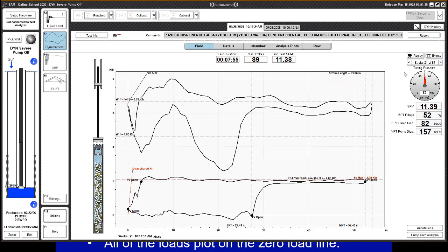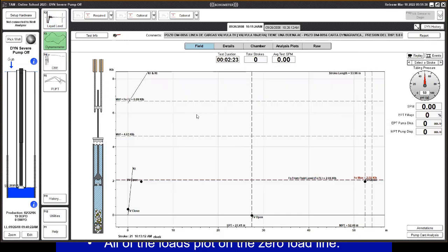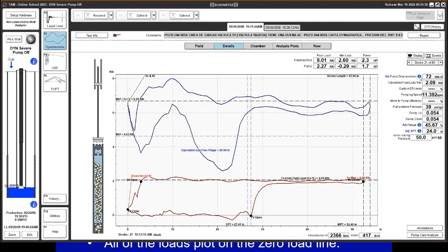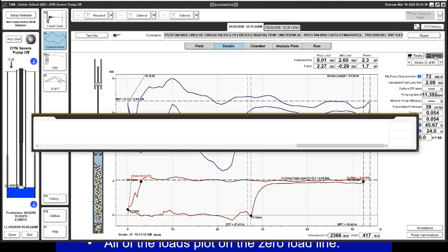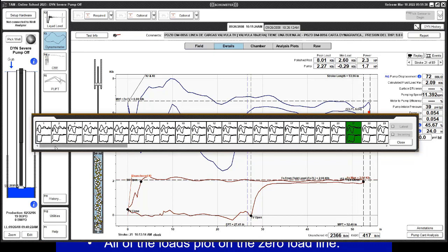Remember, when you are going to install the sensor, you have to stop the pumping unit. If the well is pumped off, and you can check the fluid level information, you can see some perforations, and this well didn't have good details on the perforations, deep fluid level. Looking at the dyno card, you can tell, well, it's pumped off, but I should be producing 52%, equivalent to 82 barrels per day. When you come to the detail view, adjusting by slippage and an anchor pump and so on, you should still be having like 72 barrels per day according to this dyno card. But when you look at more strokes, and that's why it's important for you to look at the events and allow the software to collect data for at least the time you had the well down.